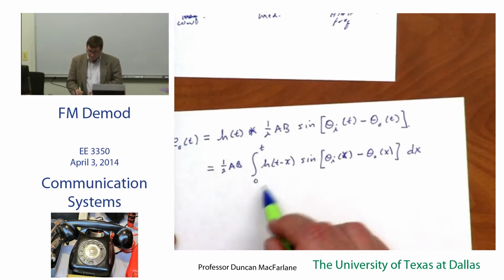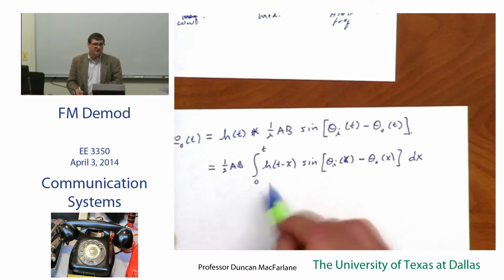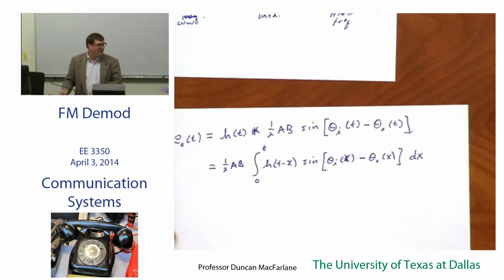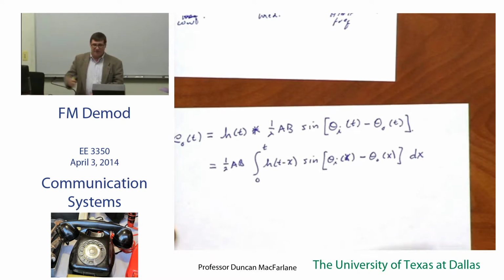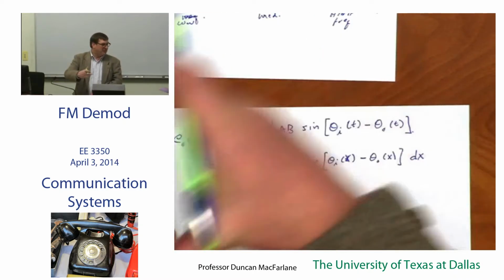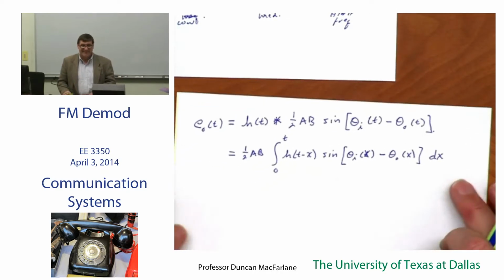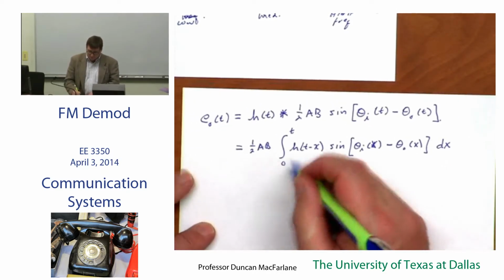Notice that I have to figure out a way to start this. It's possible to build a perfectly good phase lock loop and never have it converge into a lock because you start too far away. Okay? And that's part of the issue there.